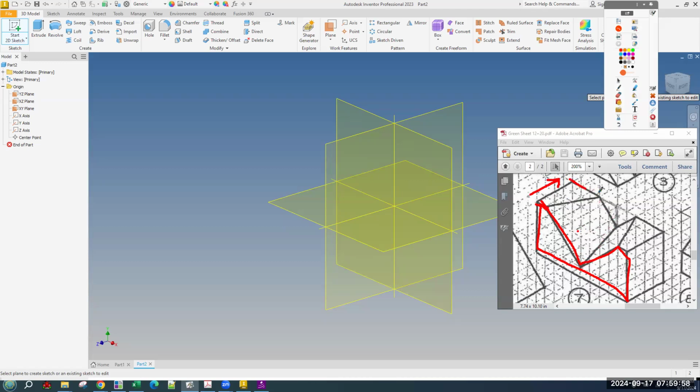And that's where we're going to draw the back as a different sketch. So this is all before we've done any extrusion. We're going to have 2 sketches that are the distance of the front and the back, and then we'll loft one into the other. And as far as I know, there isn't really another way to make this one, at least the way that it looks. That is to say, correctly.